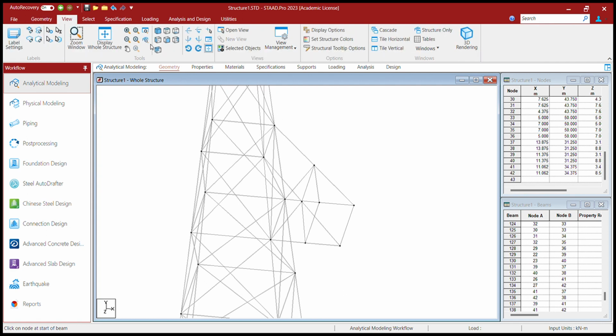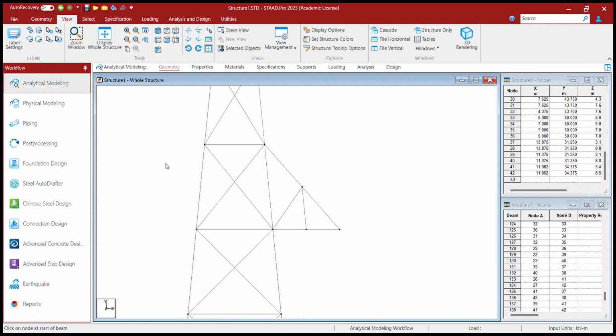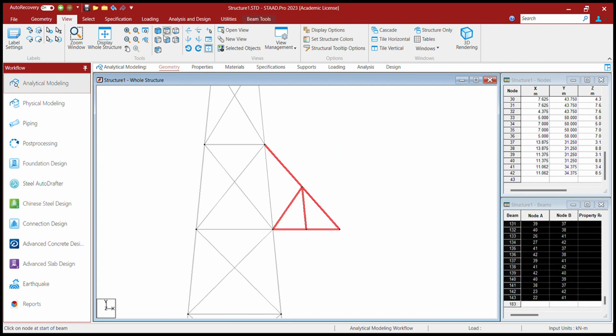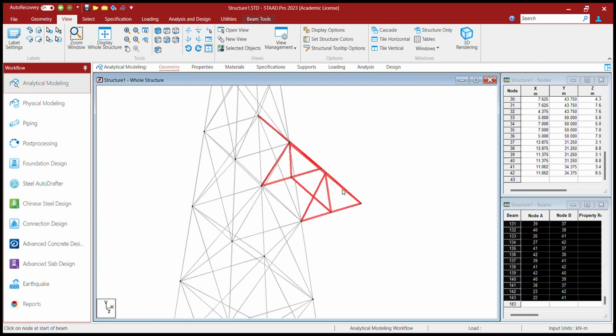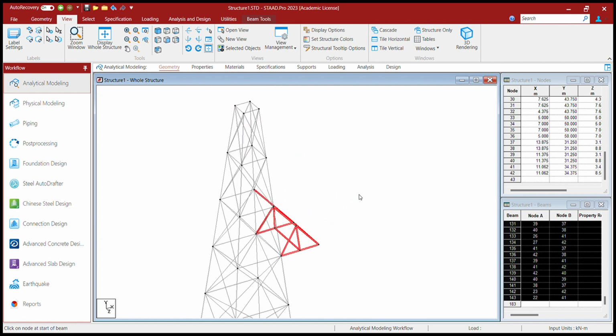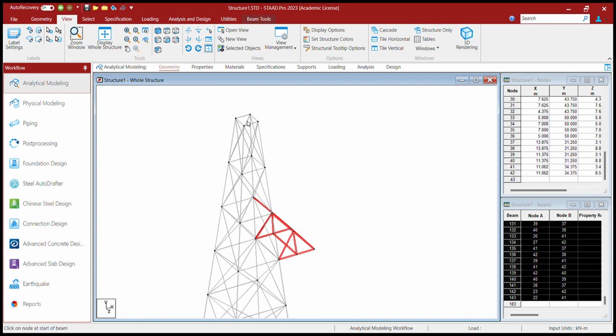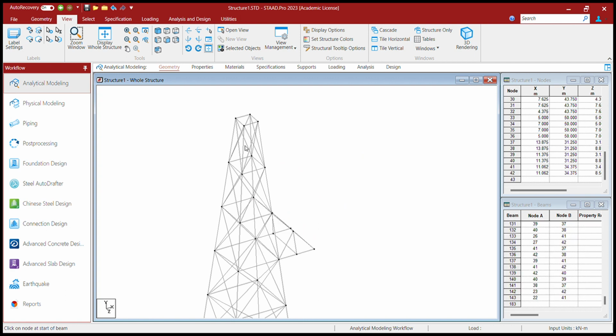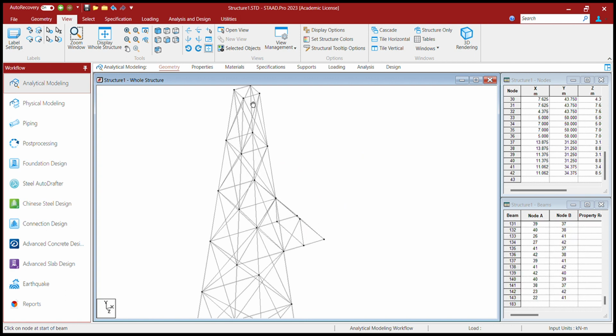So first we'll select the front view. Only the cross arm members we will select, and we'll check in isometric view whether all are selected or not. Okay, in this direction. But for that, first we need a symmetrical plane here. So first deselect this and let's create one midpoint here.